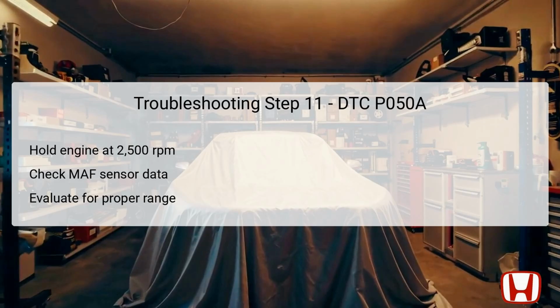If the MAF sensor's readings fall outside this range, it indicates a potential malfunction or failure. Therefore, it may become necessary to replace the MAF sensor or the integrated intake air temperature (IAT) sensor, which could contribute to the performance issues under cold start conditions.